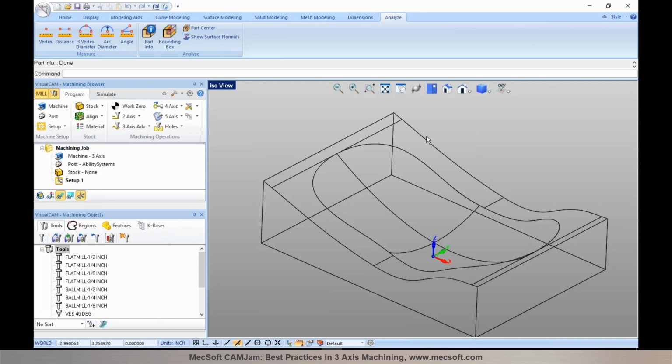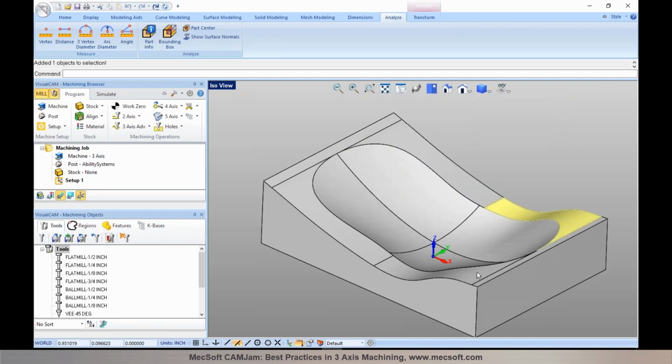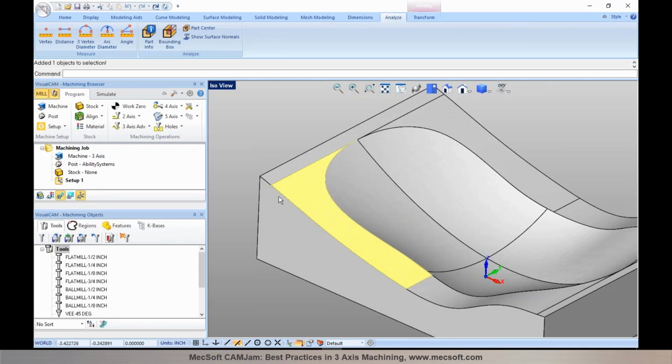So what we looked at here is an IGES model, and in the case of an IGES part, you can see that each of these are individual surfaces in here. So basically they're represented by individual surfaces. They could be sharing a common edge between the adjacent surfaces. Since they are not stitched or joined together, they don't form a polysurface.